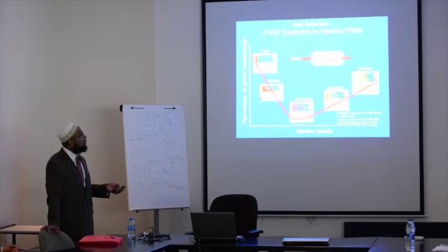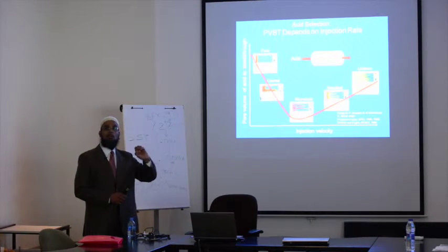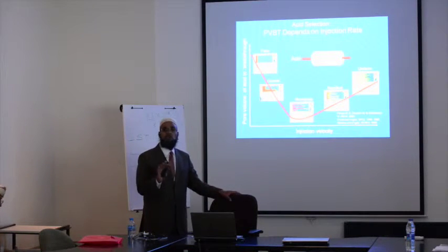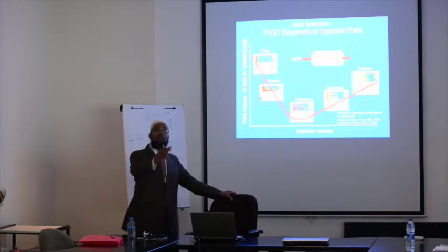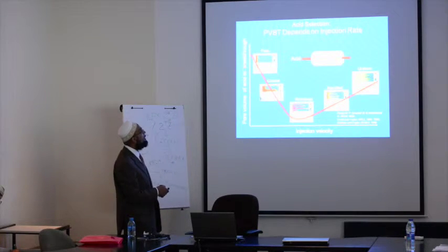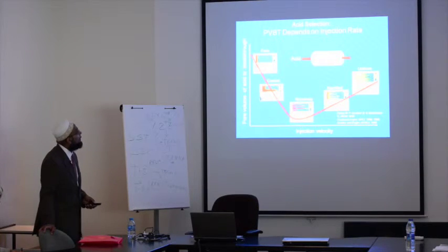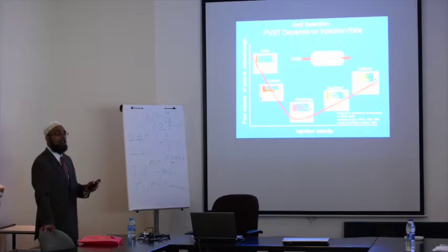Compared to something like this over here, where you get a wormhole, a straight, not many branches wormhole, and if you have a good, thin, long wormhole, we only dissolve about 2 to 3% of the rock, right? So the acid can go very deep in the formation compared to here. So if it's 2 or 3% here, 100% over here, it is 50 times more efficient, right?